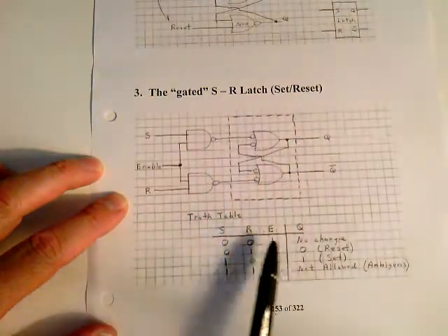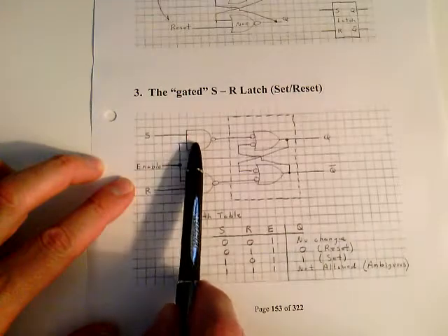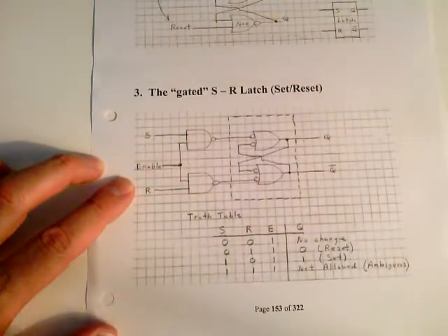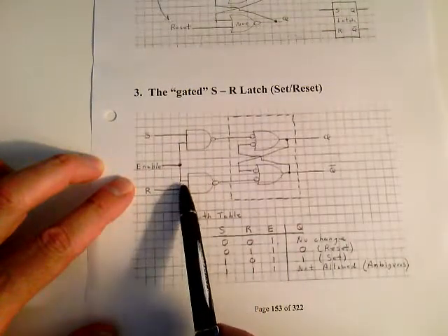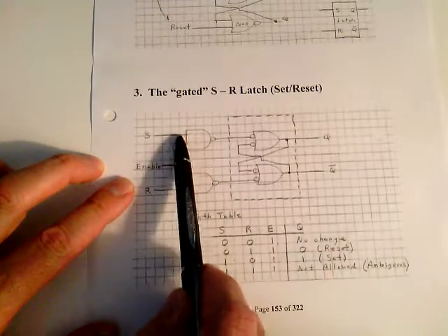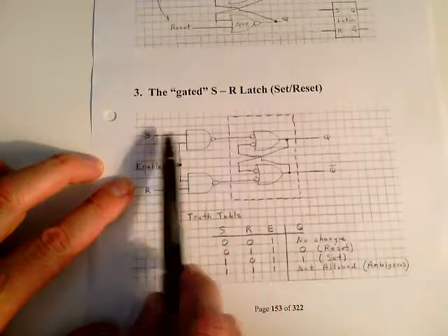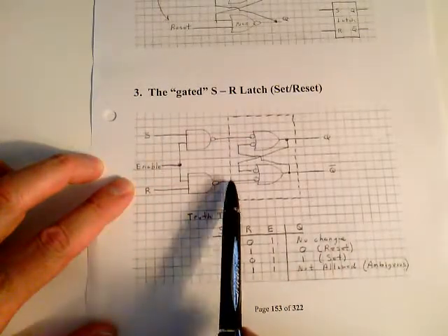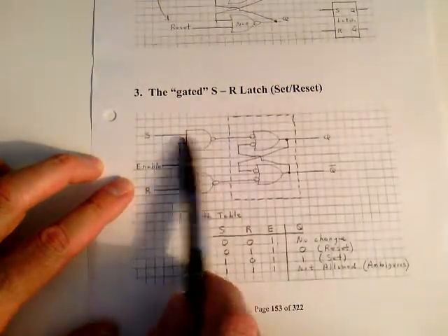So back here, if you take a look at the truth table, in order for this flip-flop to work, enable has to be a 1. There has to be a 1 on enable, so it turns this gate on and turns this gate on, or it enables this gate and enables this gate. The 1 at that pin here and the 1 at this pin here will enable these gates. And notice it places an inversion. If this was a low active set, this will be high active set here. If this was a low active reset or clear, this will be a high active here because the NAND gate basically gives it an inversion.